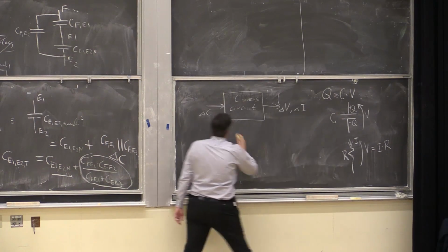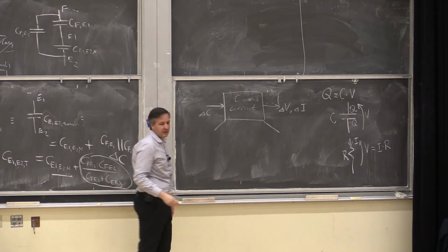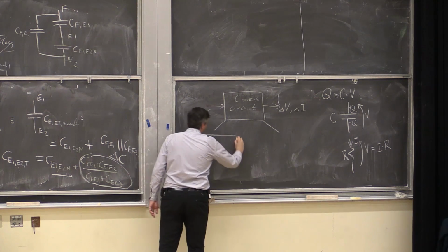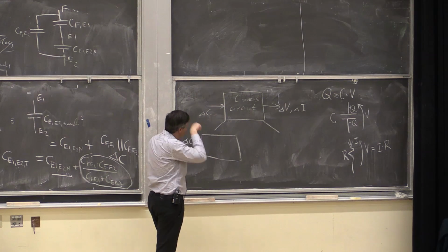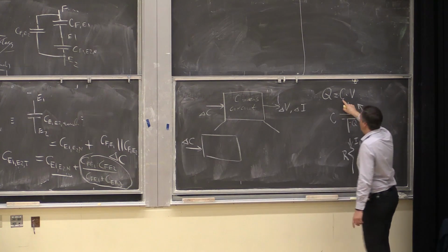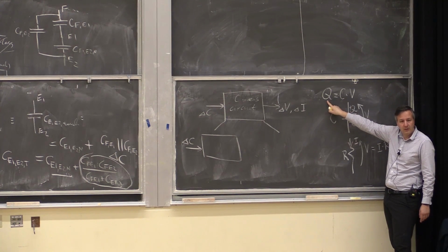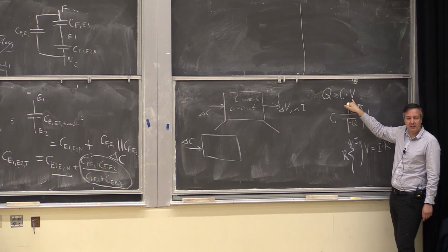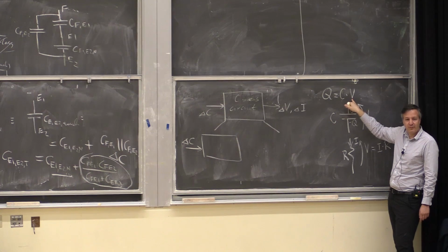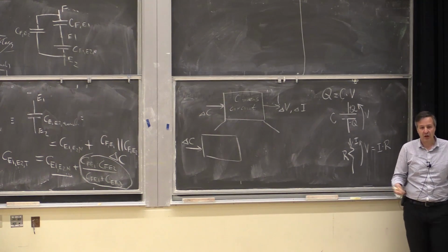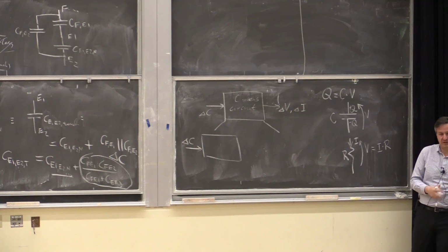So with this, we can explode a little bit what's inside this circuit. If I get delta C in, the first thing I'm going to do is try to turn a change in capacitance into a change in charge. If I want to do that, what does voltage have to be on that capacitor? I want C to change, I want Q to change. What does V have to be? Constant, right? Because if V changes, then I don't know which changed. Did C change or V change?